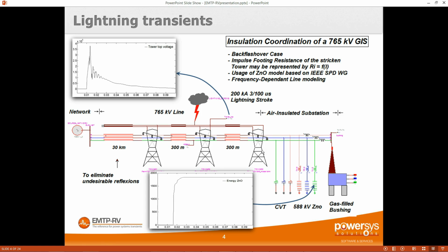Here, for example, in this case, we apply the lightning at the tower top. Very close, there is a substation. Usually we don't study really the lightning striking on the substation because they are protected against that. But the worst case scenario is when the lightning strikes very close to it. So here we put this worst case scenario as the lightning striking the tower top after one span of the substation. So you see locally each span is modeled, and even the tower.